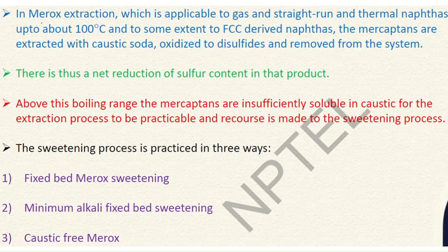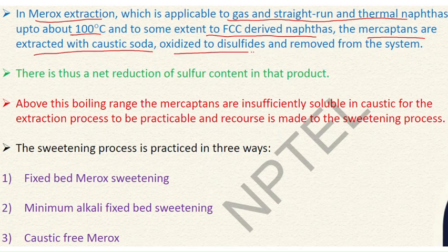Another procedure is the Merox extraction. That is the Merox process. This is Merox extraction, which is applicable to gas and straight run and thermal naphthas up to 100 degrees C. But the limitation of Merox extraction is that the cuts which have a boiling point only up to 100 degrees C can be processed under the Merox extraction procedure. And to some extent, to FCC derived naphthas, the mercaptans are extracted with caustic soda, oxidized to disulfides and